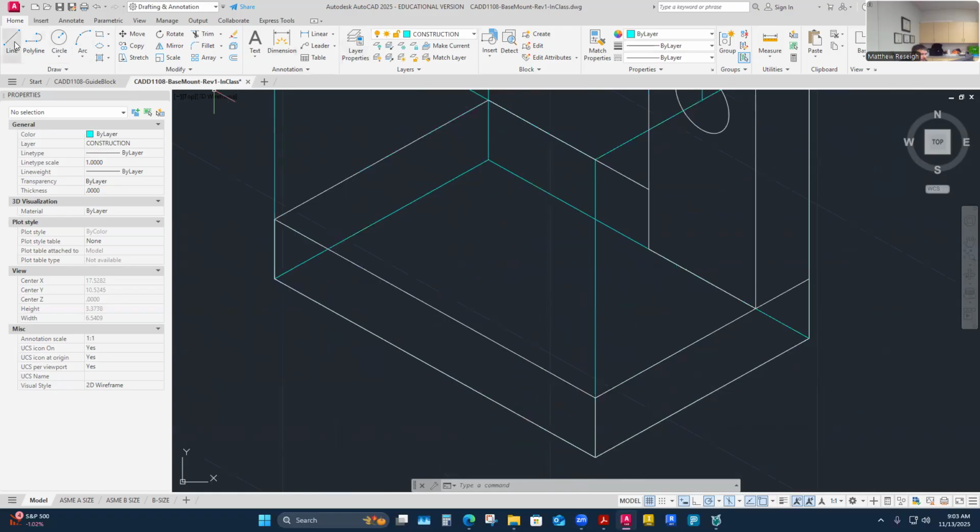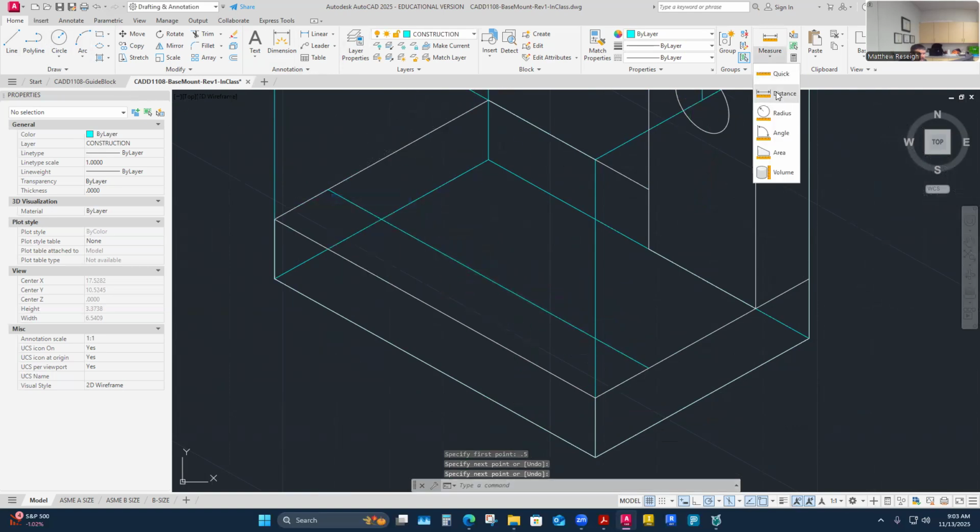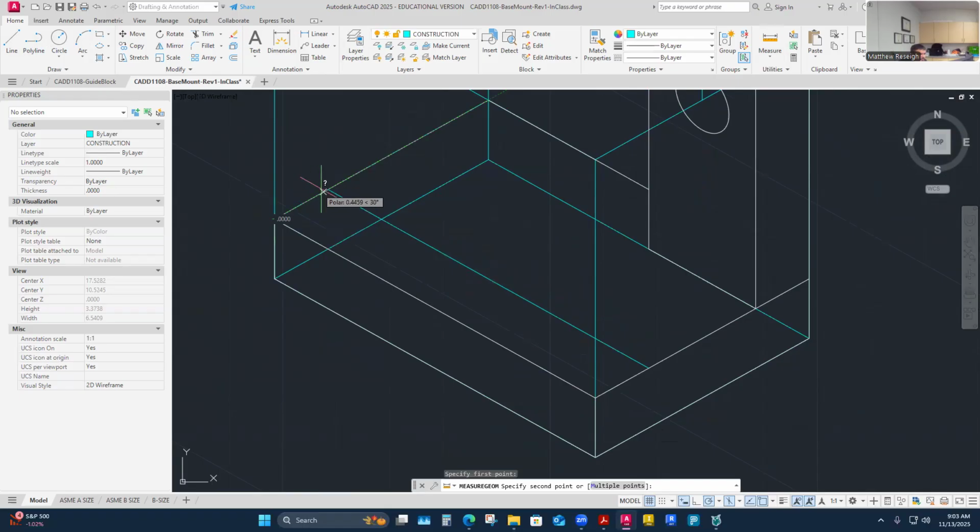I actually do the due diligence to say, well, the center line would be a half inch over here, and then it's going to be this way. And I can just stay on that 30-degree projection plane like that, snap it in there. So that one now, when I measure it, is an actual half inch, right? And it's just because we're drawing at full scale too.